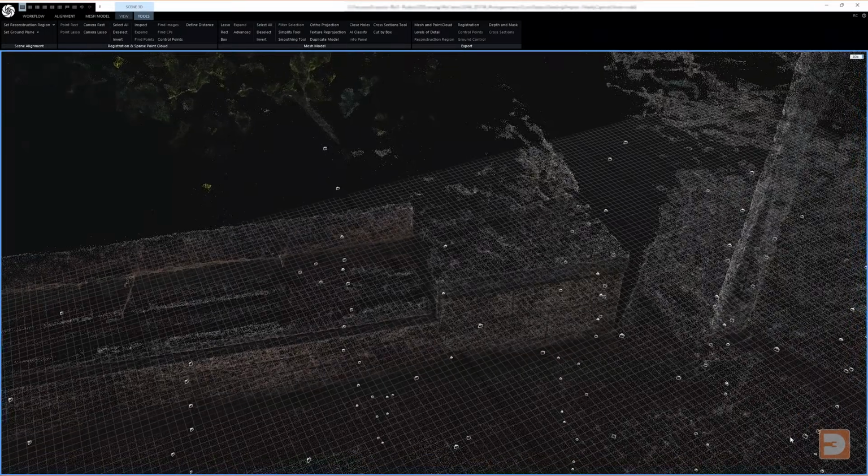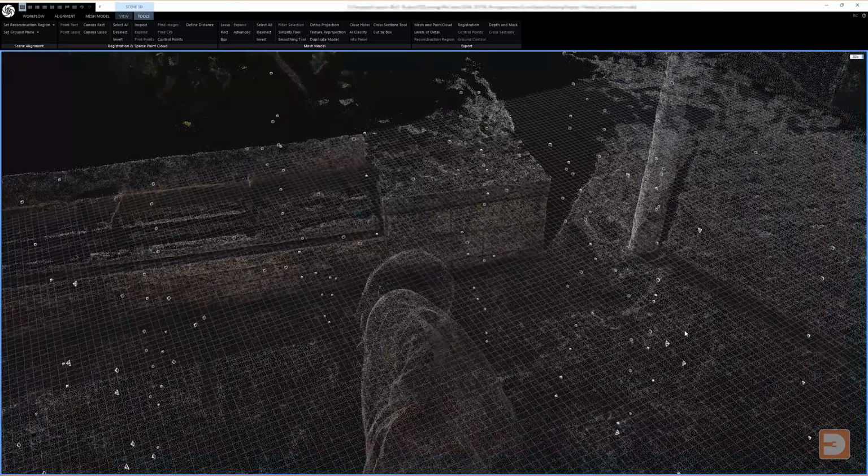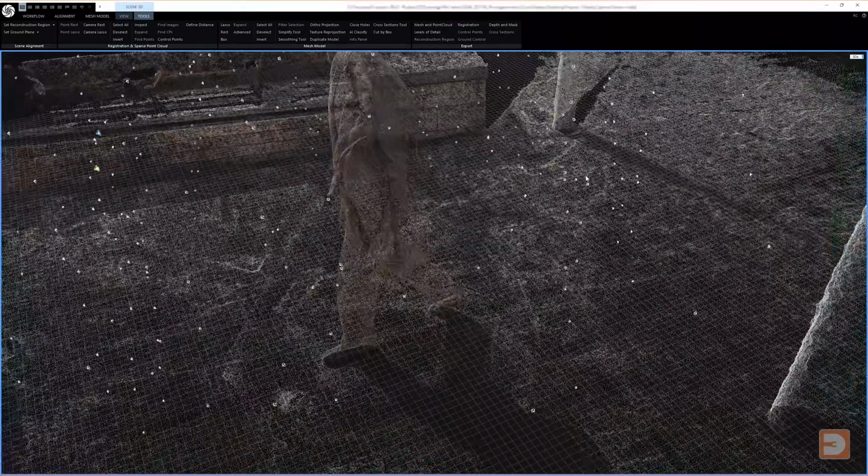So in other words, the super smart software used in modern photogrammetry is effectively following the same process that was being done entirely manually back in the 1800s, albeit with a lot more detail. Using the details that it can see in the image, as well as the image metadata which lists the camera, lens and settings used, it will also determine the relative position of the camera for each of the images. Understanding where the camera was when each of these pictures was taken will give it a better understanding of the shape of the object that they're all looking at.